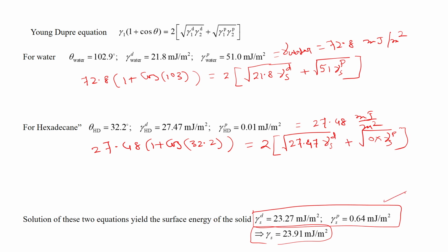So, that is the way you can use this method to measure the surface energy, and in fact two different components, the dispersive component and the polar component of the surface energy. This was quite nice and quite useful, and people use it quite often. Now, I will show you the second problem in which we would like to find out the surface energy of a liquid whose surface energy is not known.